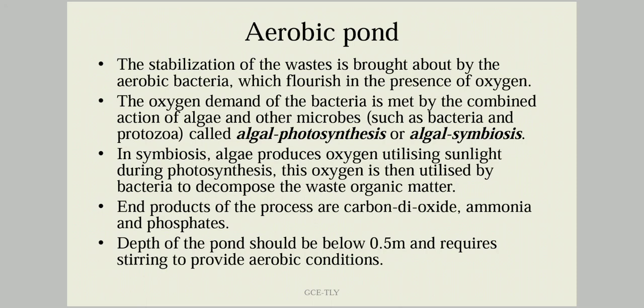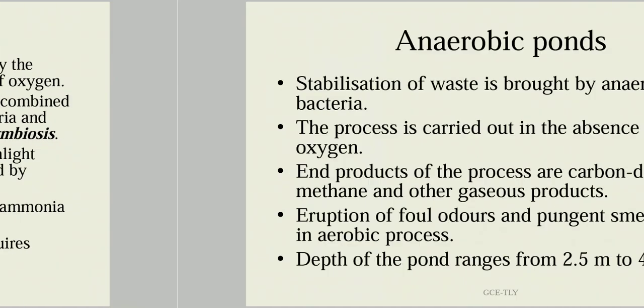Here the depth is below 0.5 meter, and it requires stirring to provide the aerobic condition. An aerobic pond is usually shallow, since in order to maintain the aerobic condition it is made shallow, with a depth below 0.5 meters, and it requires stirring to provide the aerobic condition.